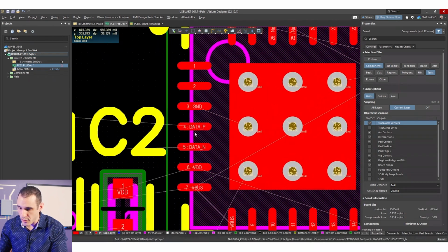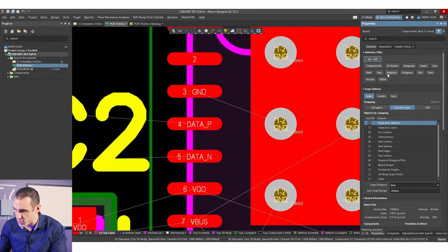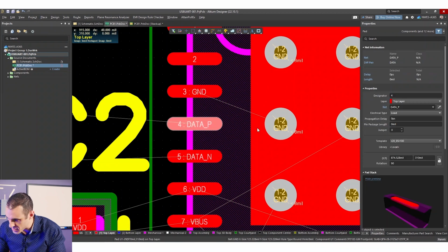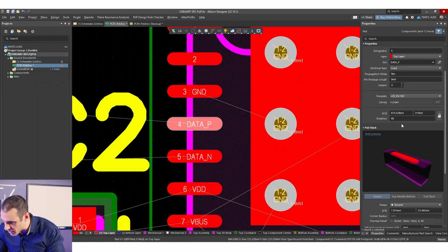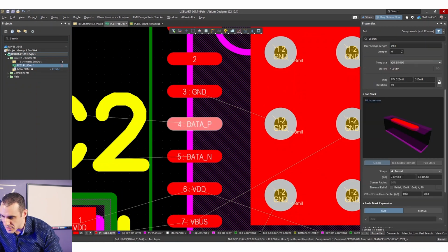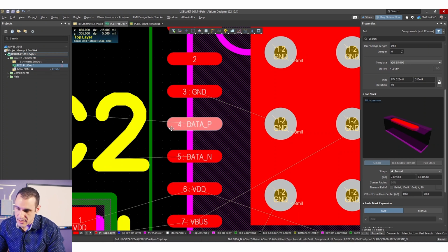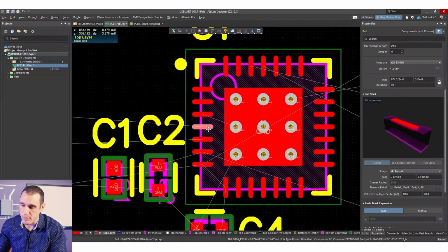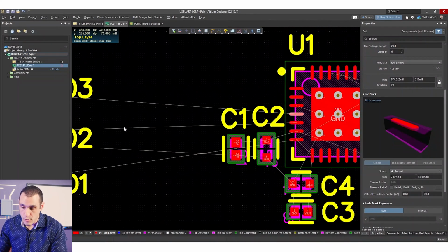And then going over here to these pads, in fact, I'll just use the selection filter and select this pad. You can see here that we're going to be a little bit larger than the actual pad size, but we're definitely not going to break through any clearance issues between pads. So we can route in 9 or 10 mil wide traces into the two data connections on the chip, and we'll be just fine. Then we'll put ground pour on the top layer to provide the ground reference that these lines require.